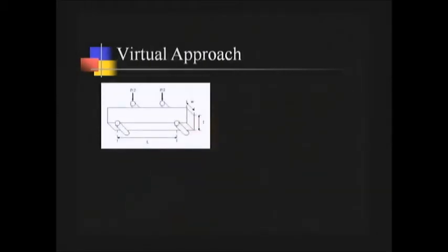So just briefly, in the virtual approach, in that method, we don't actually test a restoration in the laboratory. Instead, we shape the material into the shape of standardized specimens with an ideal geometry. For example, some of these 3-point, or in this case 4-point flexure bars that you have seen from the other presenters this morning. And then we subject that to a bending force, and it causes the stress to develop on the bottom and the material to crack.